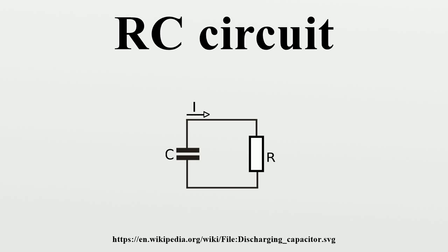When the voltage source is replaced with a short circuit, with C fully charged, the voltage across C drops exponentially with τ from V towards zero. C will be discharged to about 36.8% after τ, and essentially fully discharged after about 5τ. Note that the current in the circuit behaves as the voltage across R does, via Ohm's law. These results may also be derived by solving the differential equations describing the circuit, and the first equation is solved by using an integrating factor and the second follows easily. The solutions are exactly the same as those obtained via Laplace transforms.